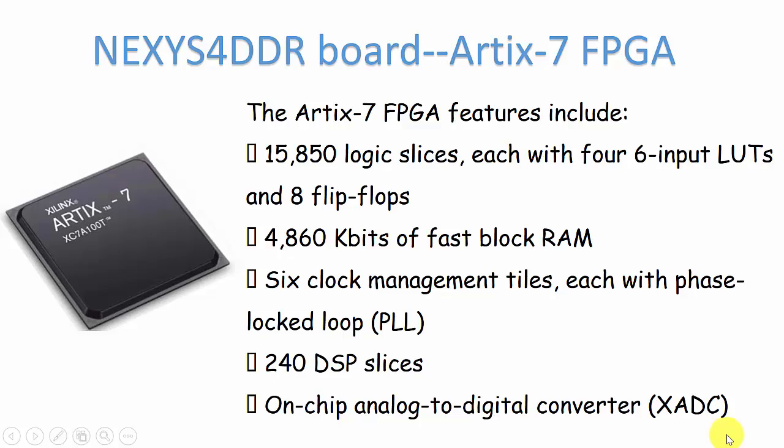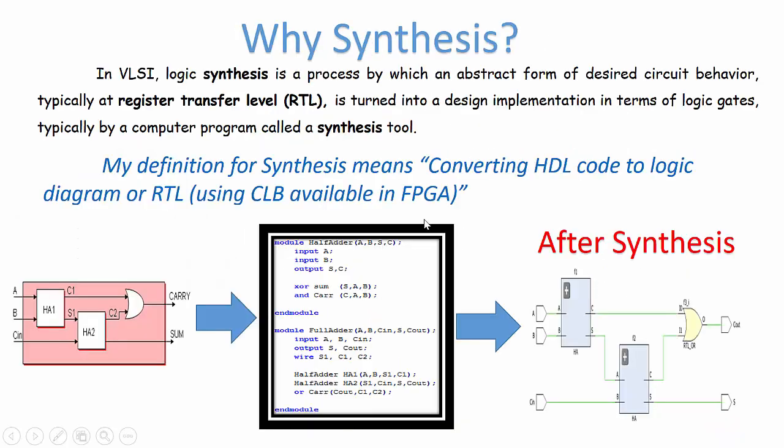Now we will discuss synthesis. This is the definition of synthesis given in Wikipedia, and I don't want to discuss that. I want to say what synthesis means in simple words. In my view, synthesis means converting the HDL code into a logic diagram, and that logic diagram is developed using the CLBs available in the FPGA.